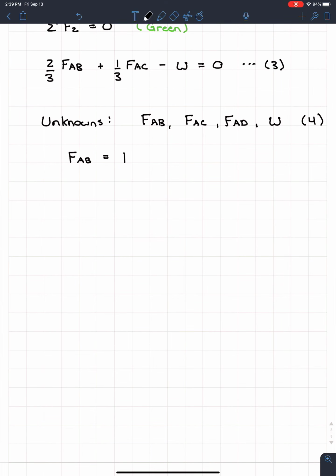So from there, let's say I get FAC is equal to 2. What I can do is I can say, okay, FAC will always be twice as great as FAB. So from there, I can say, okay, well, if I times the 2 by 225, I get that 450 newtons. That was our maximum. And I can do the same thing here, times 225, to get 225 newtons. So I know that when FAC is 450, FAB is going to be 225. And we'll kind of go through this after, but I don't know this yet.